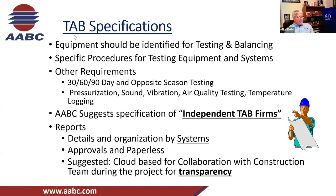TAB specifications. Equipment should be identified for testing and balancing, meaning all equipment should be listed as to what should be tested and what shouldn't. It shouldn't be assumed that all equipment on the job is just going to be tested. If there's any kind of special systems beyond air handling units, maybe it's a dust collection unit, maybe it's an isolation room, maybe it's a fan, maybe it's a HEPA filter of some sort, those should be spelled out, with specific procedures for any testing equipment.